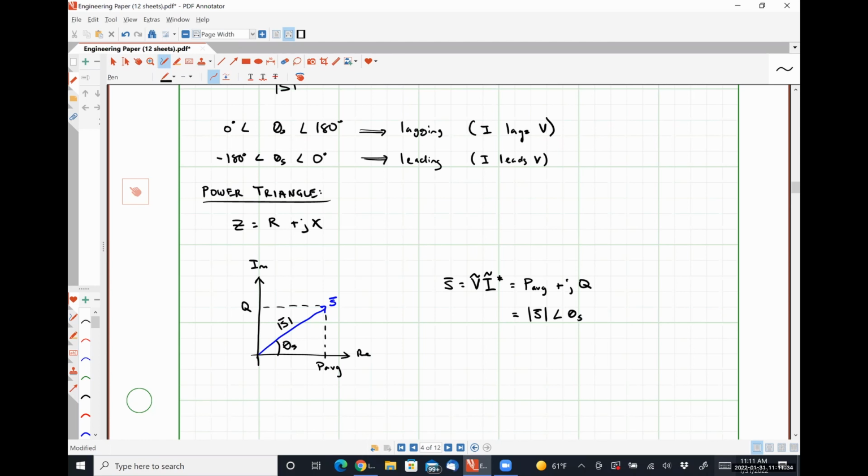And generally speaking, that's done by measuring a couple of different things, right? So if you know the zero crossings for the voltage and the current, effectively you can say, all right, every time my voltage signal is zero but increasing, I give myself a timestamp. And every time my current is zero and increasing, I give myself a timestamp. If you know what your frequency is, then due to that change in time, you can easily determine what your power factor angle is, and from there determine whether your system is leading or lagging, right?